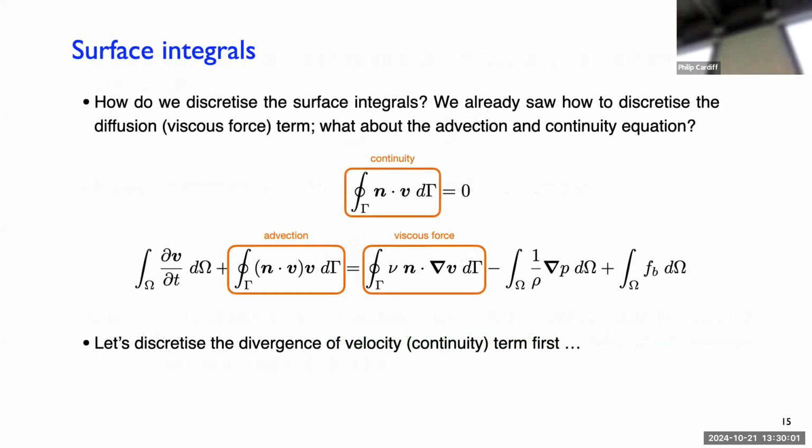All right. Back to your number 6 equations. So we've done the volume integral here for the transient term. Done the volume integral for the pressure gradient term, the pressure surface forces, although we haven't written the gradient of pressure at a cell center yet in terms of the node values or the cell center values. We've done this one, the body forces term.